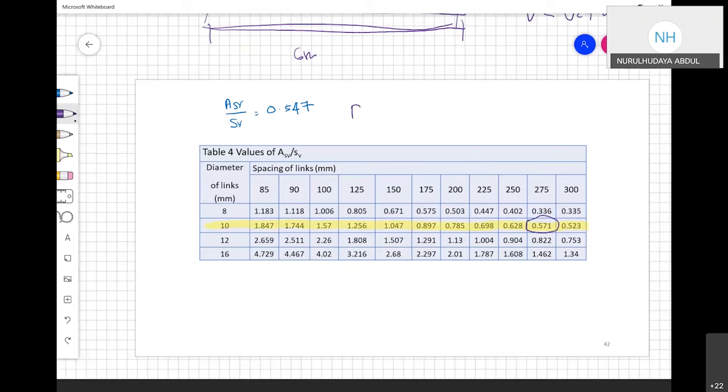Normally kita tahu kalau kita mild steel kita tulis R lah. So R10. Okay. And for link kita akan pakai by spacing bukan by number of bar. Okay, kalau by number of bar kita akan letak number kat depan ni kan. But because of spacing so kita akan tulis dash. Dash ni means refer to spacing lah. So 275. So berapa besar spacing dia tu.